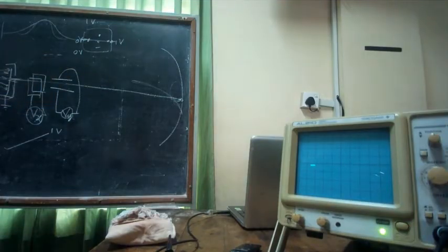So this is exactly what is happening inside this right now. There is no voltage applied on the Vy, Y plates. That is why it's on this horizontal, the 0 line, right? But it moves on this horizontal line, which means you are repeatedly applying a signal like this, right? So it's like a sawtooth.